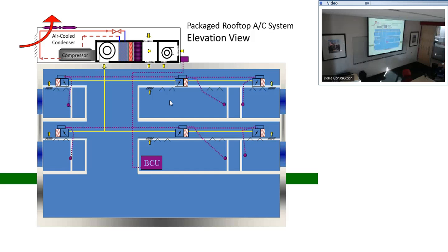Yeah, the first step is just reduce air quantity, again, because you just don't want it. What we call CV reheat is when you keep it at constant volume and reheat it, and you don't want to do that. It's not actually allowed by code. Right. And VAV stands for variable air volume. So you're controlling temperature by varying the amount of air.